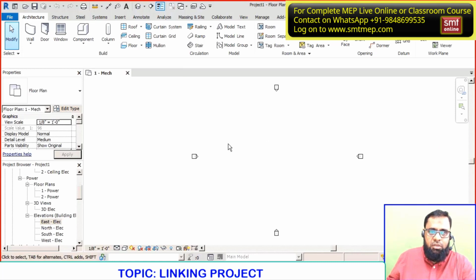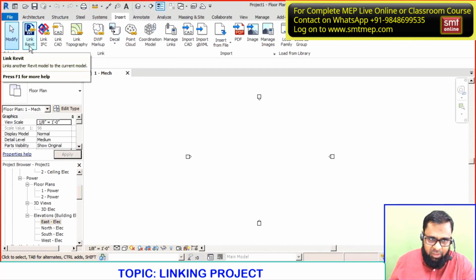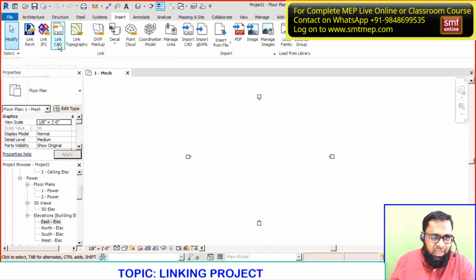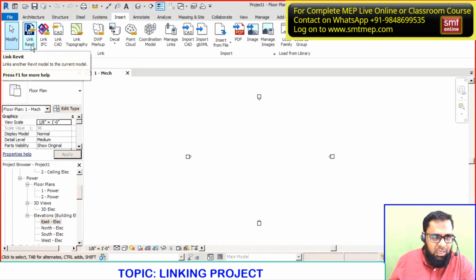Okay. So how to link? Simple. Click on the Insert tab. From this Link panel, find Link Revit. You'll find an option for Link CAD also, that we'll discuss in a separate additional topic, and for all additional topics you'll get the video to download. Okay, so here, Link Revit.